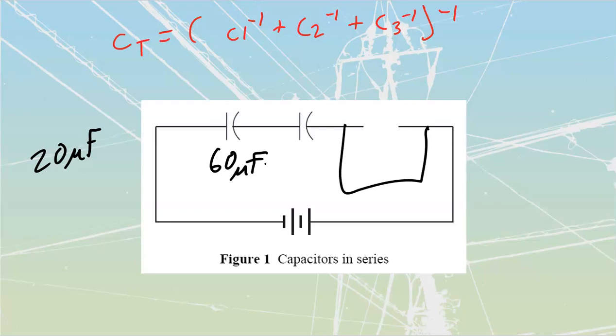Once again, if you're given this on an exam, you punch in the 4 answers to double check it. But in a case like this, where you need to actually calculate it, you will have to work these things to that common denominator. The way that you're going to work them to a common denominator is you're just going to find a number that they're all going to work with. Now we know that 1 over top of CT is equal to 1 over top of C1 plus 1 over top of C2. What we don't know yet is what C2 is.